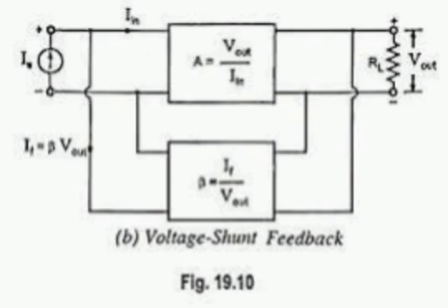CN appears parallel to CDS. Therefore, the net output capacitance will be C0 equal to CDS plus CN. C0 equal to CDS plus CGD.